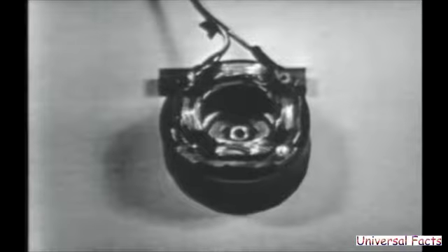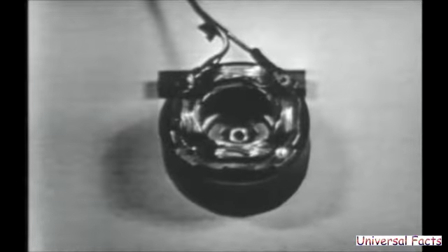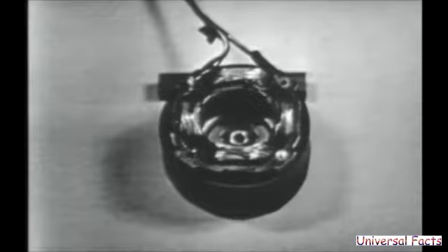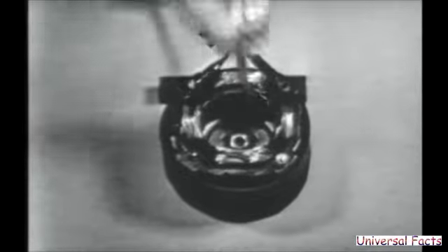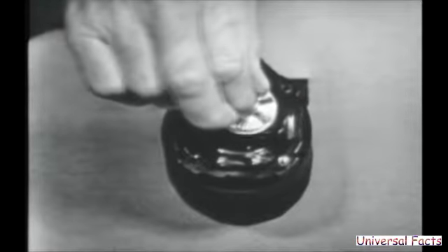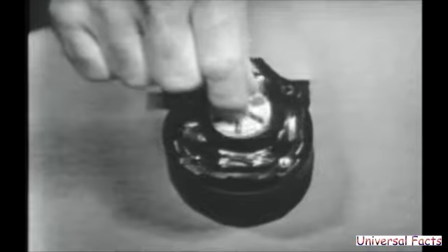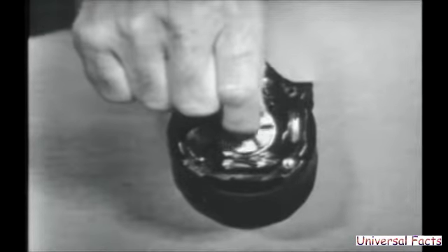I'll start over. These field windings have AC applied to them in the proper phase relationship. They are producing a rotating magnetic field, which is easily proved when this chunk of iron is dropped into the field. Well, proved, Tom, not really easily, because the magnetic field is attracting the rotor toward the stator field.